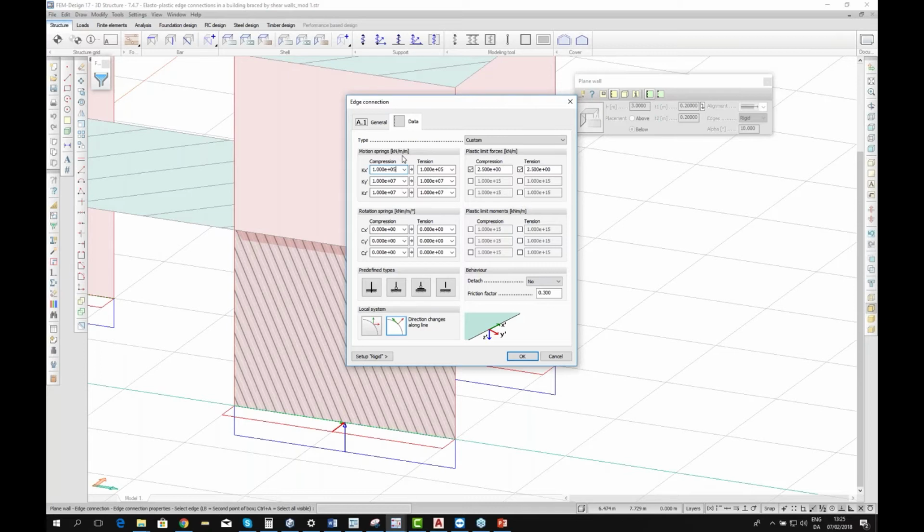That way, the deformations will occur and the nodes will be able to be activated, and so the forces transmitted. If you experience this, you might get an equilibrium error. It might be due to these stiffnesses being too high, and you need to reduce them to 10 to the power 5 from 10 to the power 7. Again, it is to allow for the deformations in the nodes.